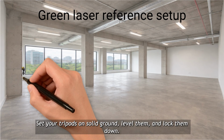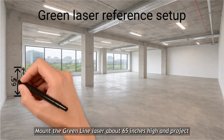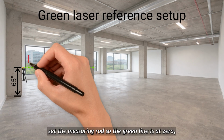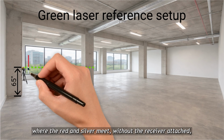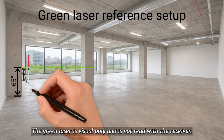Set your tripods on solid ground, level them, and lock them down. Mount the green line laser about 65 inches high and project a straight reference line. At the plan northwest corner, set the measure rod so the green line is at 0 where the red and silver meet, without the receiver attached, using the rod's adjustment knob. The green laser is visual only and is not read with the receiver.